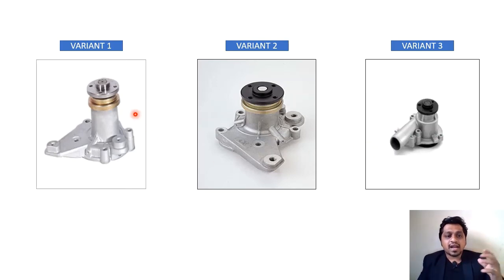And along with that, you should ask the customer that the part should have all its sub assemblies, right? That means let's consider this part. This is some kind of fitting which is attached to the job. So whether this fitting will be available when the part is loaded in the machine or not is a very important question. Because if you don't consider this and you design the fixture, and in actual use this part is present, your fixture will fail.